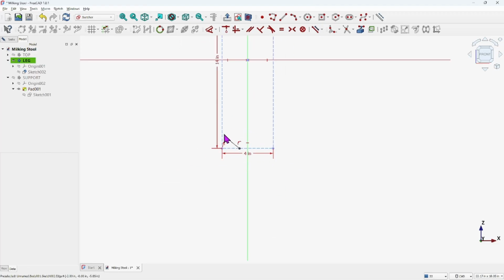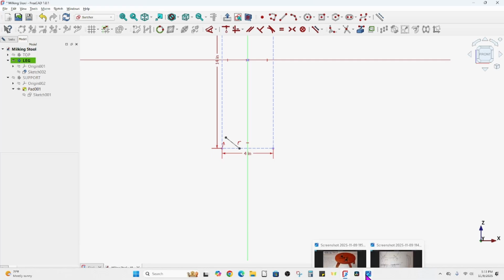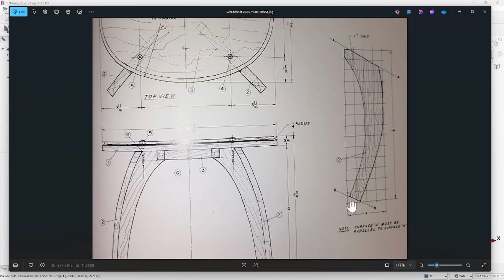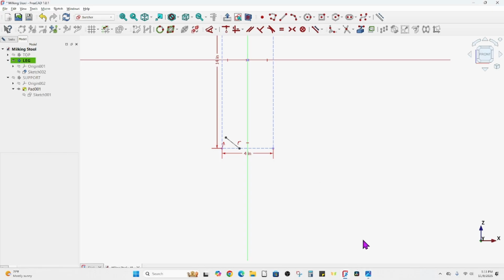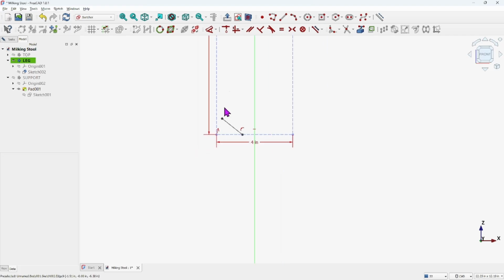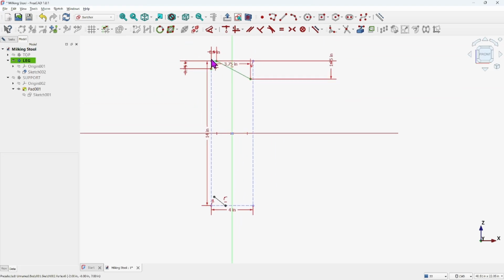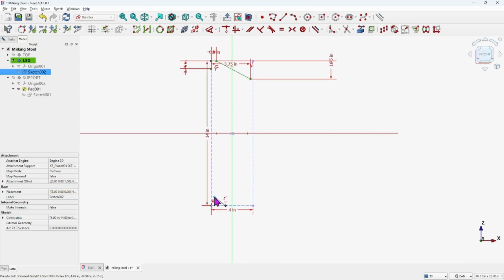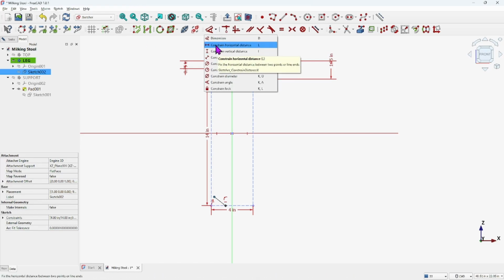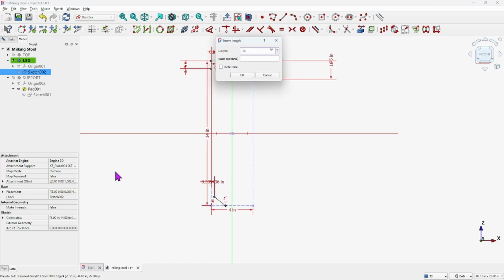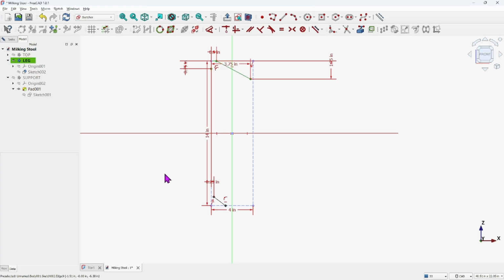All right, now let's start giving it some dimensions. I'm going to go quarter-inch horizontal, maybe 5/8 up. So again, using this point here as a reference to there, I want a horizontal of 0.25. And then I wanted 5/8 up from here.